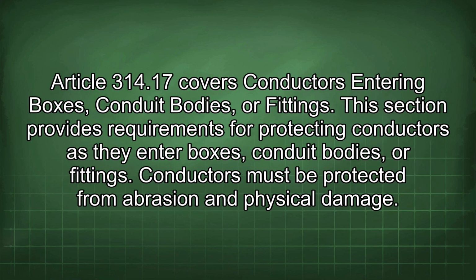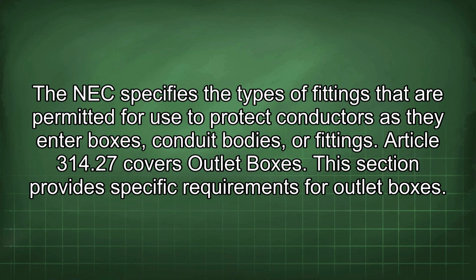Article 314.17 covers conductors entering boxes, conduit bodies, or fittings. This section provides requirements for protecting conductors as they enter boxes, conduit bodies, or fittings. Conductors must be protected from abrasion and physical damage. The NEC specifies the types of fittings that are permitted for use to protect conductors as they enter boxes, conduit bodies, or fittings.